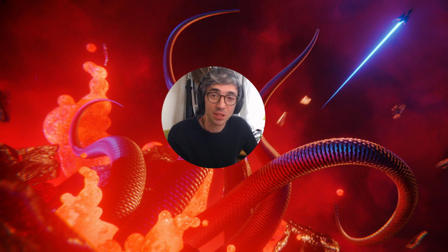Great. Now let's come over to the material tab. I'm going to click new to create a new material, and I'm just going to work with an emission shader for now. So I'll delete that, create an emission shader, and plug it into the surface.